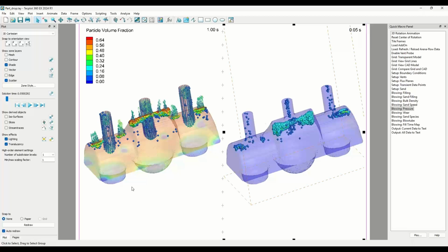Let's say I'm speculating it could be asking about core gas generation. If you have a varying density in the core, and then you're running a core gas model, that's not specifically what it says, but I'm wondering if that's what's meant. In which case, it's my understanding that you can view things in Tecplot, but there are always ways to get the raw data out. This would probably involve some scripting, but you could dump that raw data, the particle density and volume fraction locations, and if there's a way to import that into the other software, then that could be done, because it is possible to export.